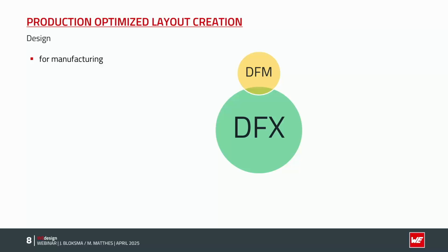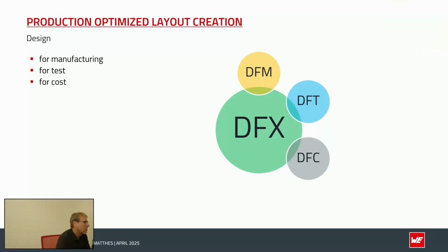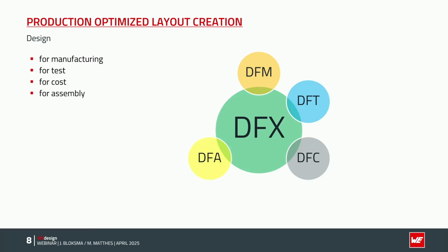When we are implementing projects, we are guided by the objectives agreed with the customer, and generally follow the DFX approaches to generate the optimum result for the customer. For example, the DFM, design for manufacturing, is a topic we need to take care of. Testability is also a point: which kind of tests do you need after the population of the PCB? Design for cost is a point; you need to get a PCB that's as cheap as possible, so we need to take care of this. Design for assembly, and also design for reliability.